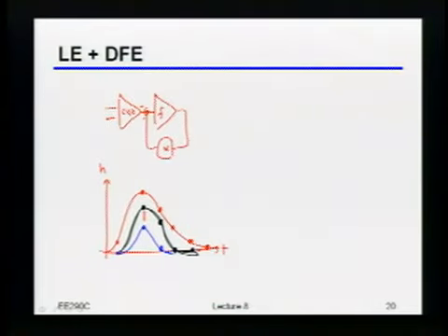Okay? So when you combine these two things, you want to set things based upon knowing how many DFE taps you're going to be using. You also want to build your linear equalizer keeping that in mind. And I'll just mention this briefly. It turns out a lot of times people will do these DFEs not because it's actually thermal noise that's being amplified that causes a problem, but just because there's a lot of crosstalk that you might be picking up at the input of the CTLE.